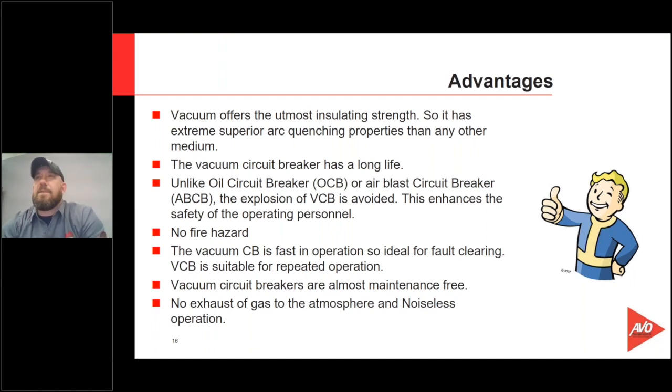Some of these bottles are good for 10,000, 15,000 operations. Unlike old circuit breakers or air blast circuit breakers, the explosion of a vacuum circuit breaker, a vacuum interrupter, is avoided. This enhances the safety of the operating personnel. It's quiet, all right. It's maintenance free, almost maintenance free.